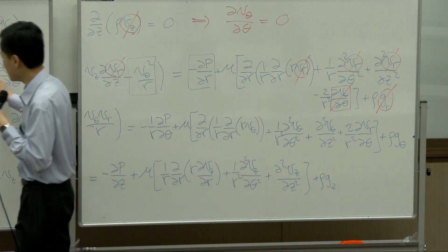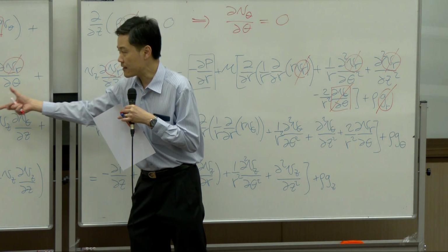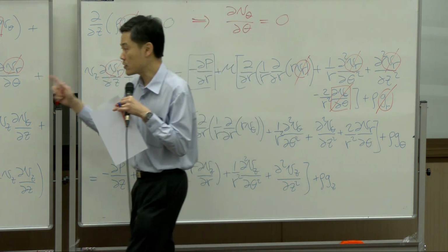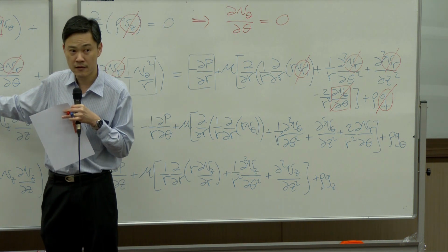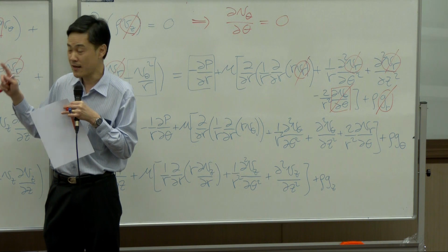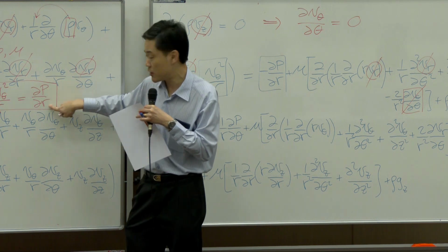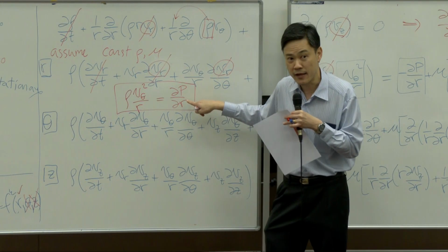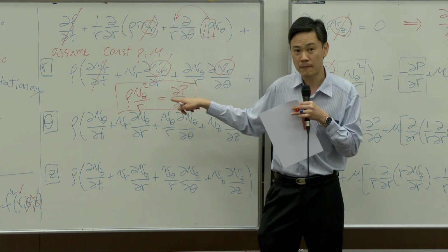So this is what you will get from our equation. From this, you see that there will be a pressure gradient in R direction. In other words, the pressure gradient depends on how fast you spin, right? The faster you spin, the larger the pressure gradient. And I said, it is not pressure itself, it's the pressure gradient. This is change with respect to R. The larger the velocity V theta, the larger the pressure gradient. That is an effect that you call centrifugal force.